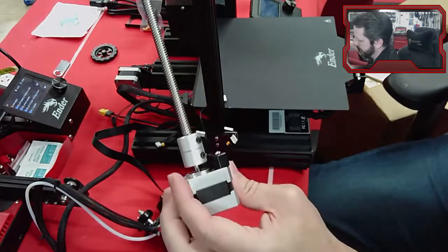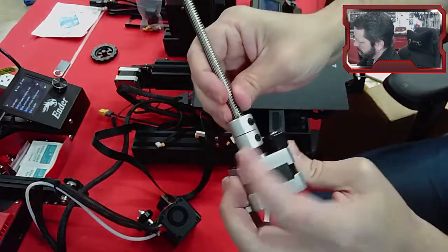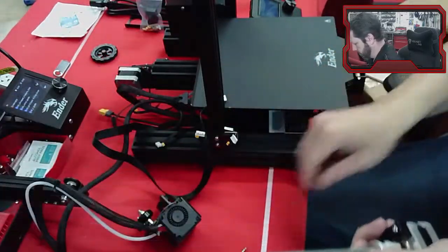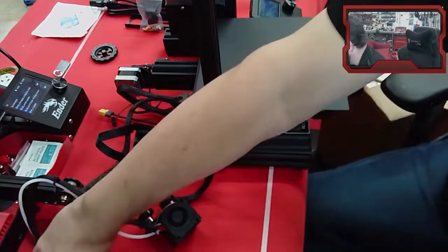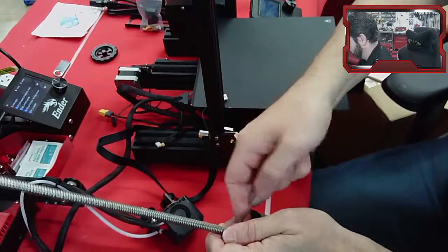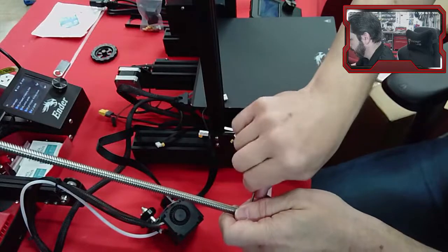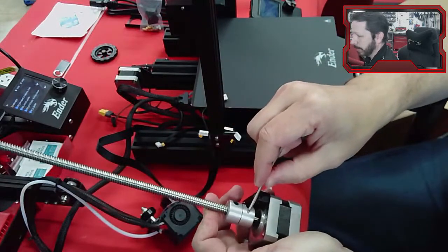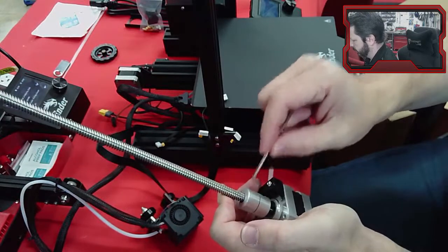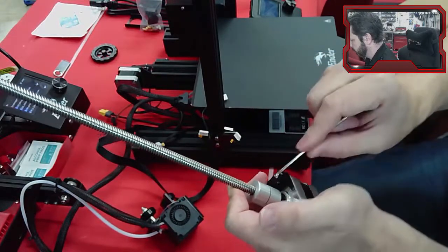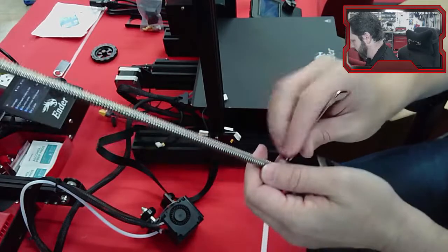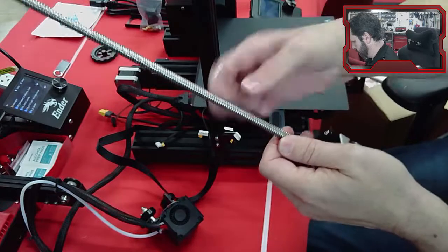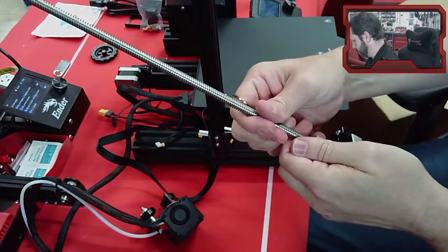And then it's going to screw into this coupler. Well, not screw into it. It's going to sit in this coupler. And then we'll tighten this set screw to hold it in place. We've got to find the right Allen wrench. You don't really want the screw to bottom out against this bottom half of the coupler. You want it to stay in its half and this one in its half, so that they're not touching each other. I think I actually have this one set a little bit low. Let's see if I can figure it out. Yeah. All right, there.